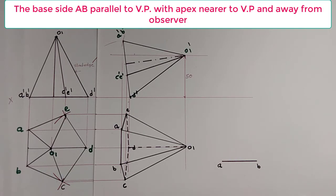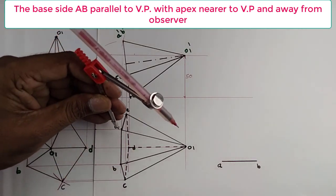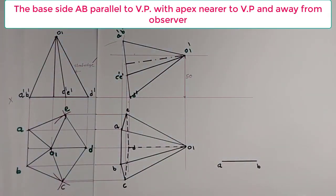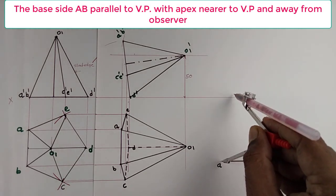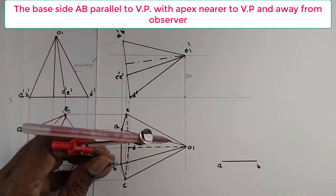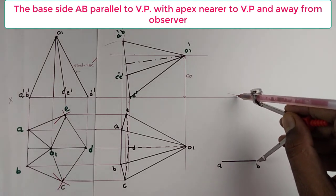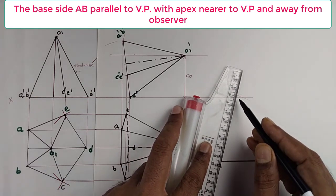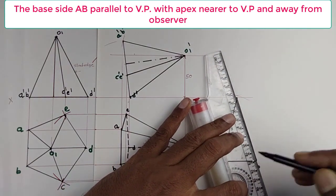Now I rearrange the second stage plan with reference to AB. First I find out AO1. From A to O1, I choose the radius. And the problem says the apex is nearer to VP plane, away from the observer, so I draw the arc on top. I join AO1 and BO1. This is my O1 point.